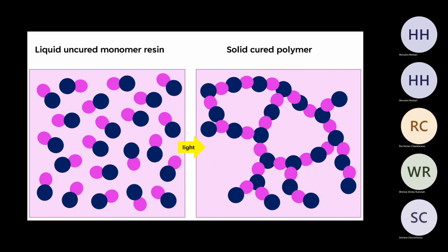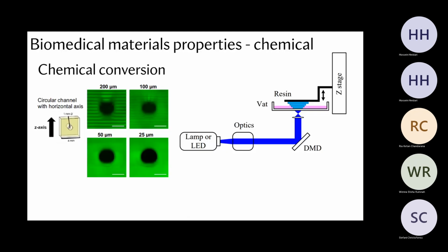Basically they can escape, and that's what makes the network extremely weak, and that's what can potentially be useful, but sometimes not that useful. So in 3D printing, what happens in practice, as I mentioned, you've got that absorber. If you look at the composition of the layers, they're going to be denser and denser towards the top of each layer, and then you're going to have a gradient of conversion, even within the single layer. Because deeper into that layer, you have lower intensity because it's dropping, because of the absorption. That's why you get those delaminations and cracks.